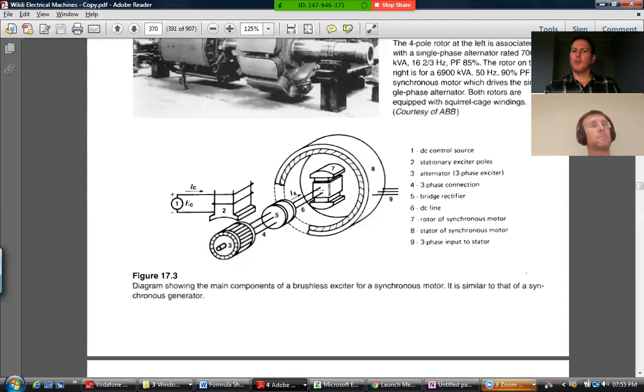And if you had a well-designed machine, it's not going to steal that much. Then, of course, there's also some friction, potentially stealing some of the torque that's produced. And there's also I squared R losses in the stator, and there's some magnetic circuit losses in the stator as well, the so-called core losses, like a transformer would have.